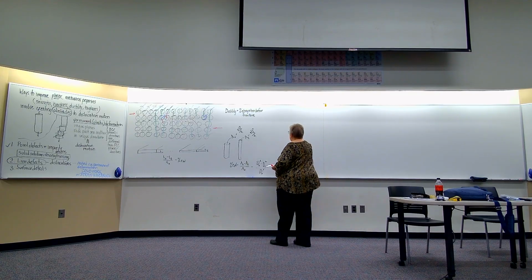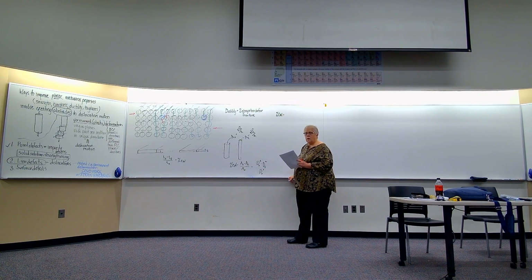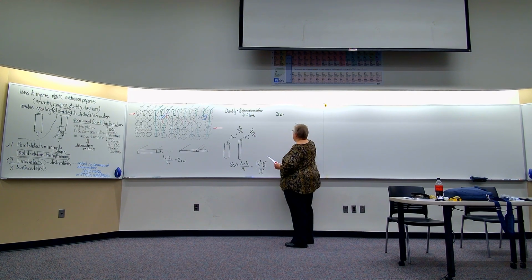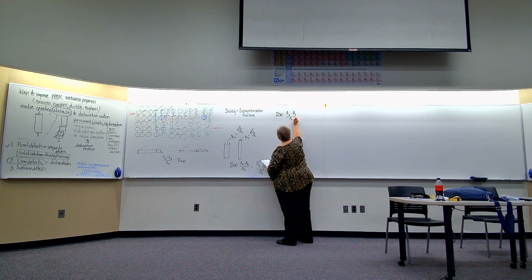So we need to determine the percent cold work. This is a round cross section, so it's the change in the diameters squared over the original diameter squared. Let's put that all there instead of just relying on A original minus A final over A original.